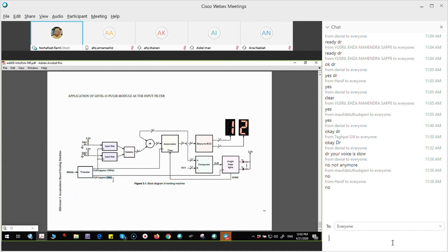Like one, another one. 1 second, right? So if your hand is faster than 1 second, you will lose your signal here. If it's a push button, when you touch and then you let go of your hand, it will let go. So if you use 1 hertz, maybe before the 1 Hz comes, you already lost your signal. That's why I suggest you increase the frequency here to 100 Hz to be able to catch your human behavior.